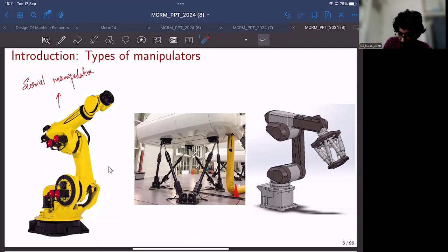Typically, the most common actuators used in these sorts of robots are rotary, probably brushless DC motors, which actuate these revolute joints, right? And they are attached one after the other. It does not even have any closed chains like a 4-bar mechanism. There are no closed loops.